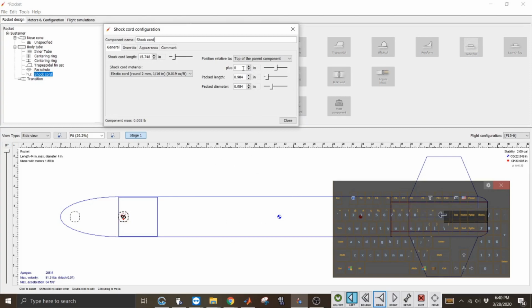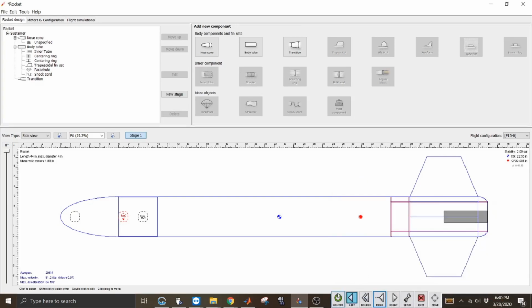And what this does is tether your parachute to the airframe. When the parachute actually fills up with air and provides a shock, the cord also has some elasticity that allows it to stretch, so the shock dissipates throughout the cord, which is nice because it creates less impact or disturbance to the frame of the rocket.